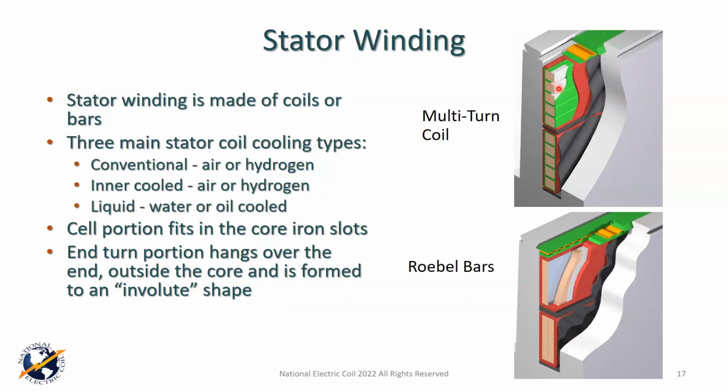Further to the slot. Now you see we have green going around each of those bundles. It's important we understand the insulation. We've got some insulation on these strands, that kind of tan color there. That can be a multitude of things, but most common in high voltage coils is what they call double Dacron glass. It's just Dacron glass that's wrapped around them. And the Dacron component in that material, through heat, is fused together. There are usually 2 layers. That's why they call it DDG or double Dacron glass.